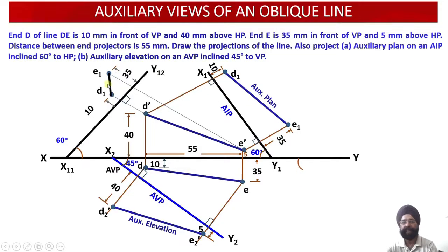So just compare this view of the line with this view. This view is much shorter than this view. That is why we are not inclined to draw this view. Even though this is technically correct, it gives us a poor, unsatisfactory solution, because you are getting a smaller view of the line.